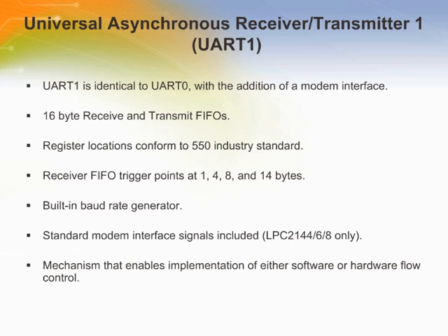The UART1 transmitter block, U1TX, accepts data written by the CPU or host and buffers the data in the UART1 TX holding register FIFO, U1THR. The UART1 TX shift register, U1TSR, reads the data stored in the U1THR and assembles the data to transmit via the serial output pin TXD1.